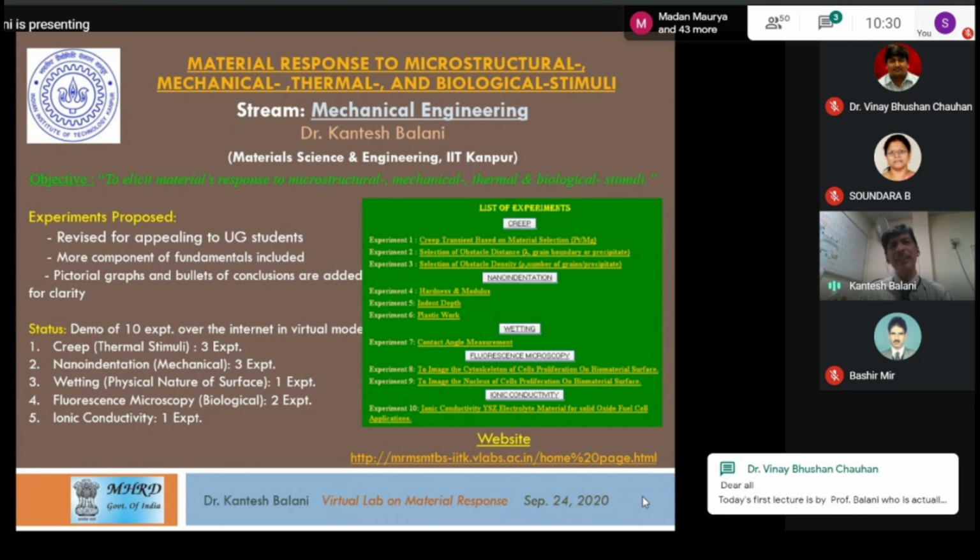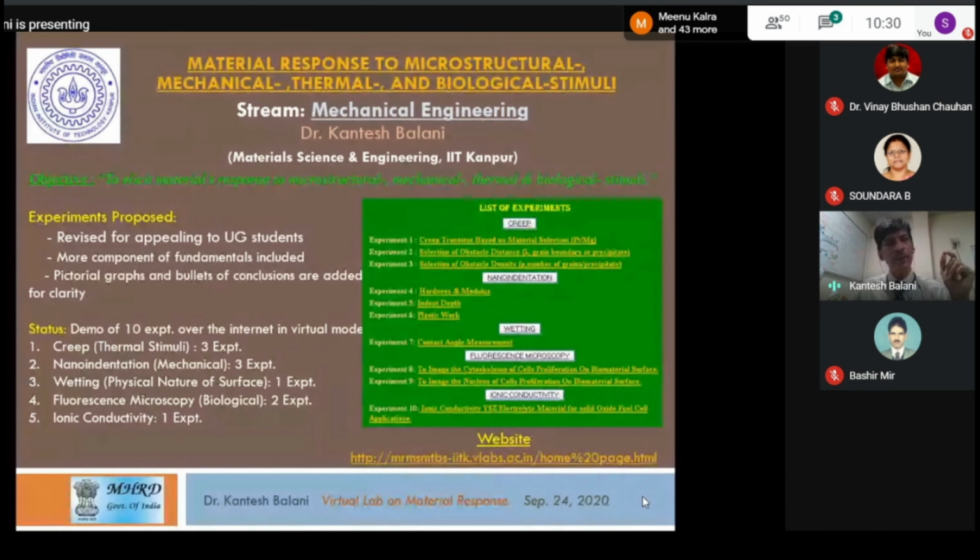The second aspect is the mechanical and thermal load. You might still remember the twin towers catastrophe. The twin towers were designed to hold the impact, but it was the burning fuel that lowered the strength of the aluminum frames, because the aluminum had to bear high temperature, and then it started buckling, and the entire structure collapsed.